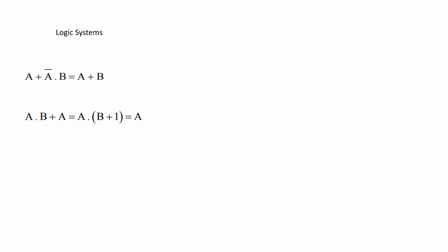Okay. Other things about logic systems. You need to know your 7 basic logic gates. You really do need to know them by now. Yeah, you need to know what they are. I'm not going to draw them all. You need to know your NAND gate conversions. Yeah. So how do I take a NAND gate? God, that's badly drawn. Put them together to make other logic gates. For example, that would be an OR gate. Yeah. You need to know how to do Karnaugh maps. Remember grouping 1s, 2s, 4s, or 8s. Hopefully straightforward. But yeah, logic system is what I call the bread and butter, really.